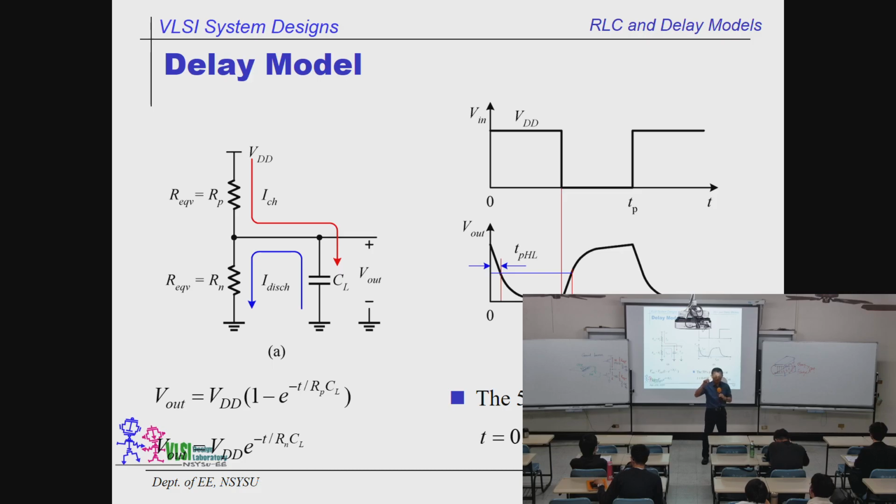Let's assume we have a very big load. Remember the load I gave to you? I assigned a homework of 0.1 pico-F, right? Check the number over here. This is a parasitic number. What is the unit over here? It's a femtofarad. It's 1,000 times of difference, so they can be ignored. The load I gave you in the homework assignment is 1 pico-F or 0.1 pico-F, and this is femtofarad, 1,000 times smaller.